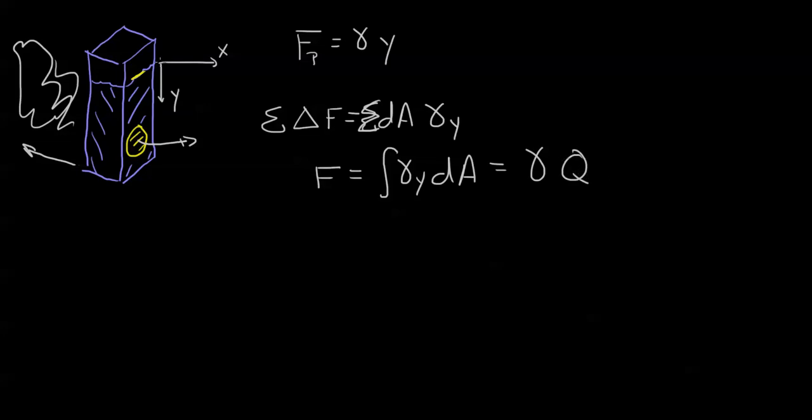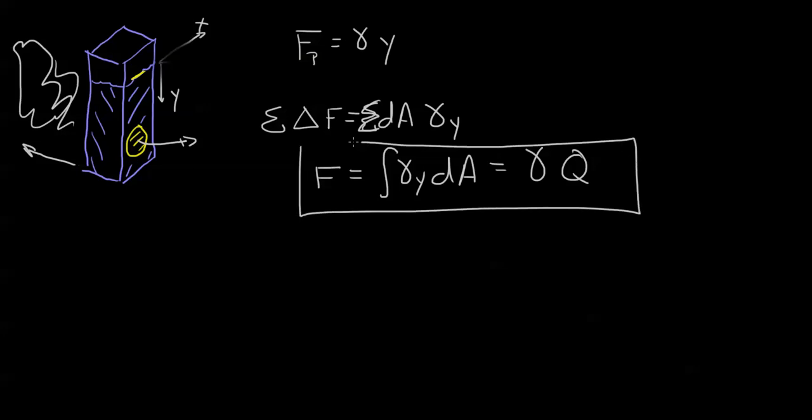Oh, and actually, I'm going to change the axis here so we're clear. That axis is x. It looks a little confusing otherwise. There we go. Now that said, this tells us the magnitude of the force. We have to integrate the area, and we can find out the magnitude of the force easily enough. But what it does not tell us is where that force is acting.